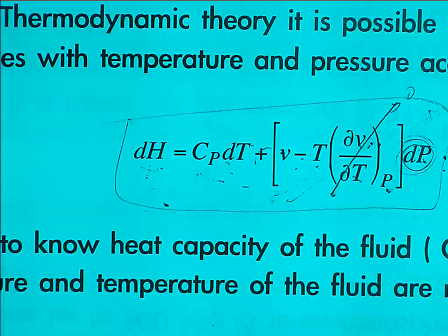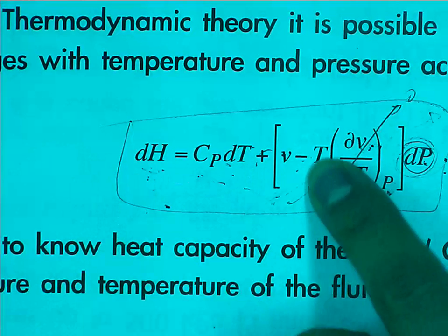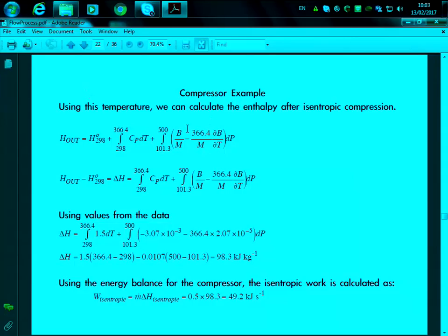So these steps go through the integration again of all the variables, and then after that just substitution of the variables in here. So 1.5 (T2 minus T1), and in here we have P2 minus P1 and all the constants that we can see in here. So that will be delta H. But what type of delta H will this be? Will this be the real delta H that you have in the system? No, it will be under isentropic conditions.